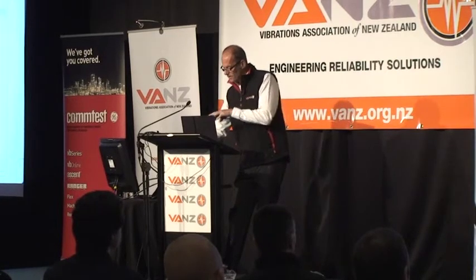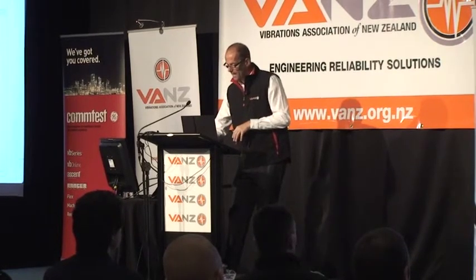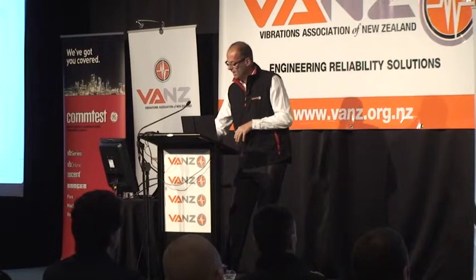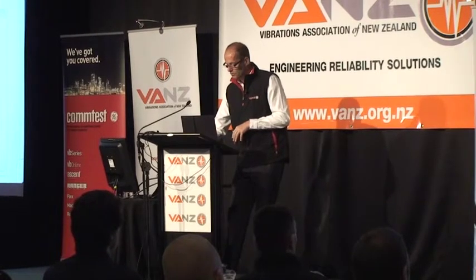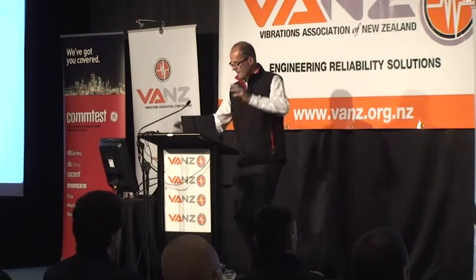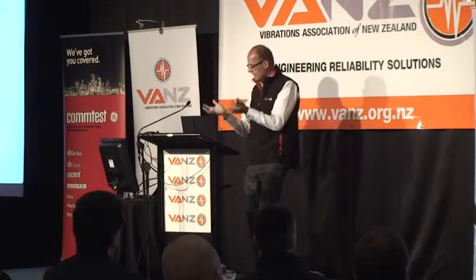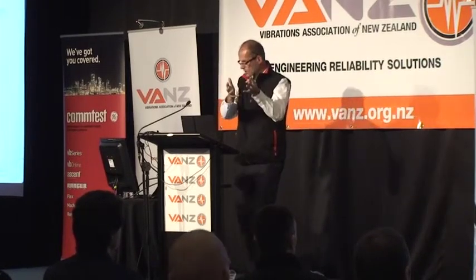With something like this, you can see this little cone there. As you increase the distance, the cone gets wider. So what you're actually measuring is maybe not what you think. You're pointing it at this conductor, but it's actually taking the temperature from a wider area, and thus you're picking up something that's hot, even though you're pointing at something that's not.